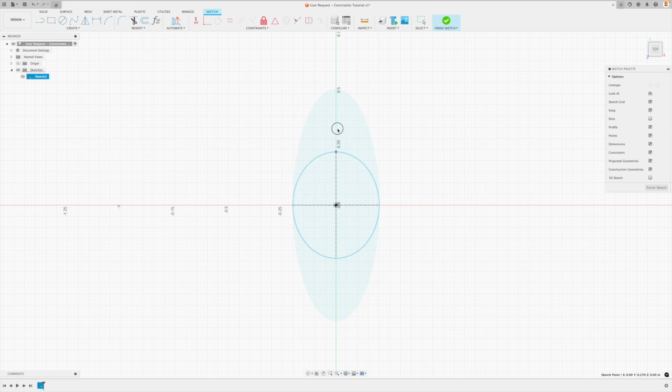Now I can just change the height, and here I can change the width of it. But interesting enough, this line is also constrained. Why? Well, it is assumed when we've got 4 lines like this that they are all perpendicular to one another. And that corresponds to another constraint, but we don't see it on the screen.